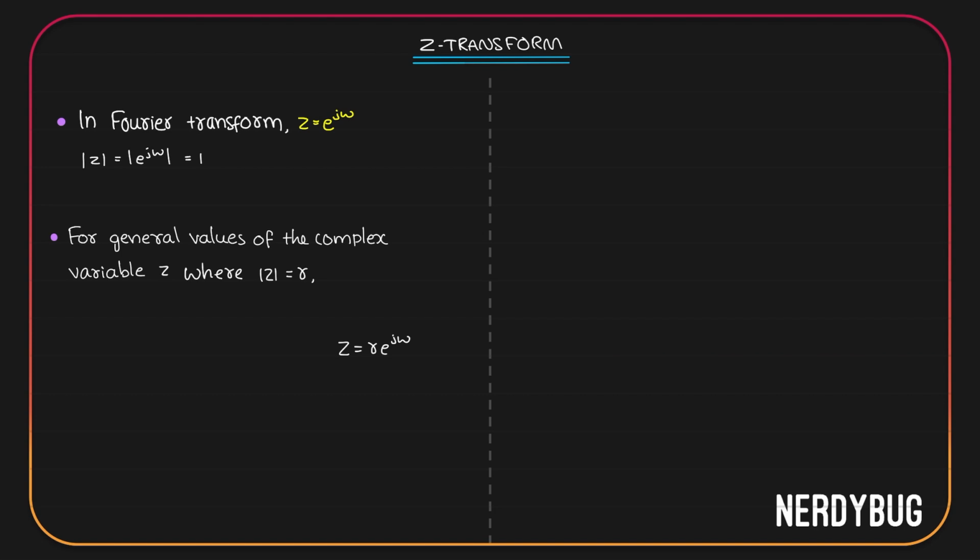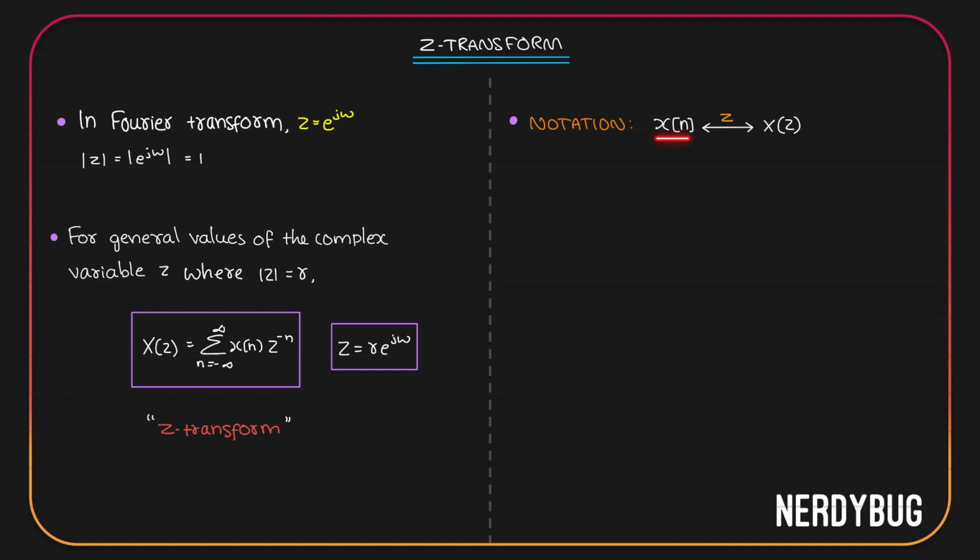In that case, we can write X of z for a discrete time signal x of n will be summation from n equals minus infinity to infinity x of n z raised to minus n. This is the same expression, but this time we are taking a general value for z where its magnitude is not equal to 1. Instead, it is something else that is called r. In that case, we can call this z transform of x of n. The relation between x of n and X of z can be denoted by using a double-sided arrow with a z on top of it.